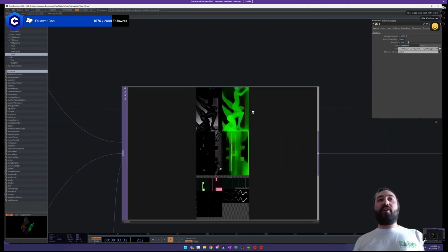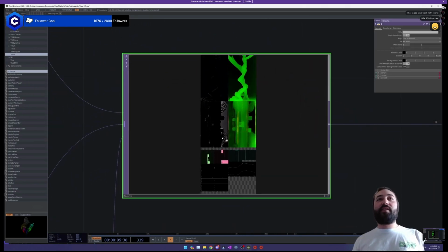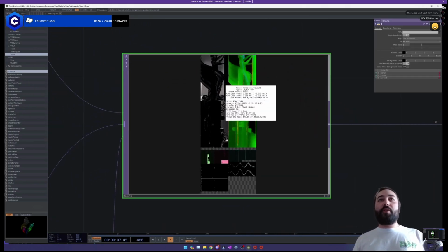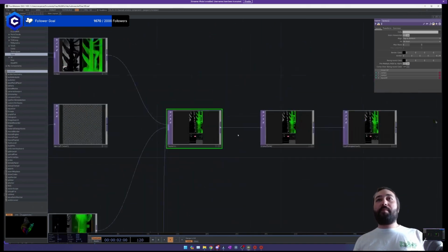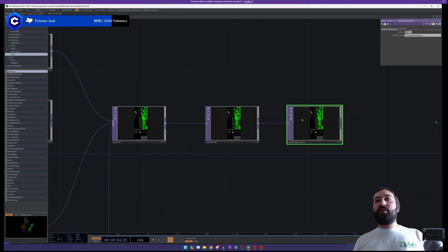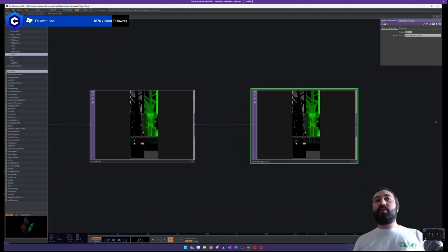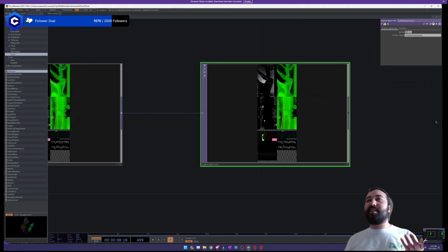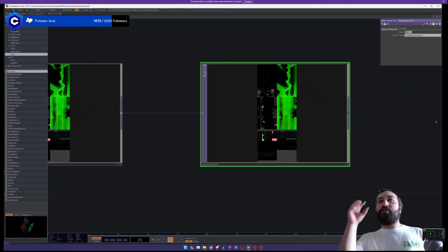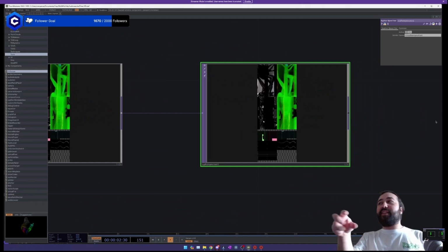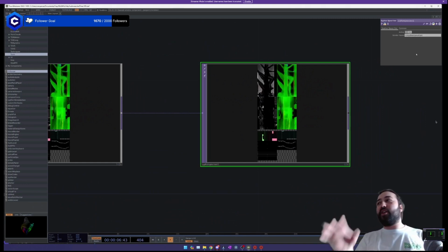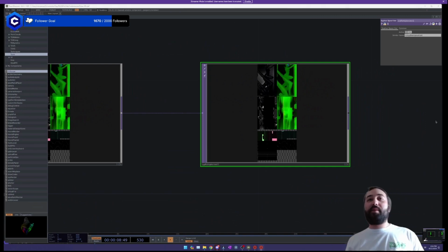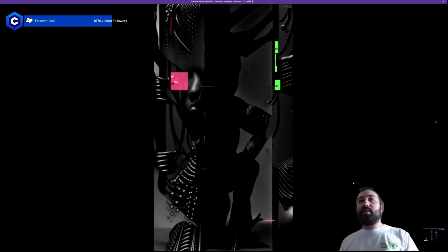So I combine all these three things together into this one 1344 by 3360 pixel map, and then this gets sent to Knotch using this node called Siphon Spout Out. What this does is it puts it somewhere in your GPU, in the memory, and then Knotch, just based on the name you put here, knows where to grab it, and then it can pick it up. So that's what this is.